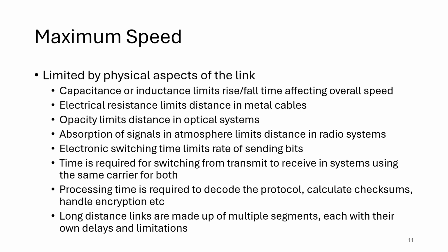You also have some systems where if you're using the same carrier for both sending and receiving, you do have to switch from transmit to receive, and that can cause timing issues. So typically, if you're using some sort of radio mechanism or a single wire, maybe on a telephone system like we used to, you would have a modem turnaround time, and that could be set to say 100 milliseconds. That would be quite a substantial time to allow the switching devices to transmit and then switch to receive, and that of course would limit your overall speed of processing time.